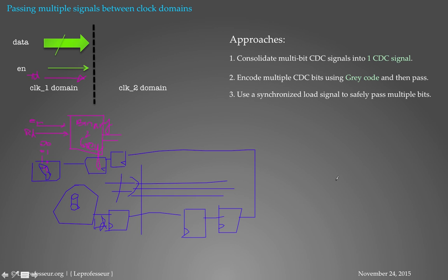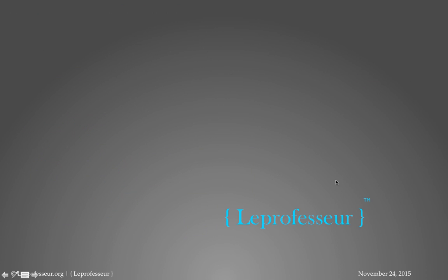So always remember that in a group of signals, only one signal should change in one clock when you are crossing from one clock domain to another clock domain. That is the basic, simple, fundamental rule to remember.